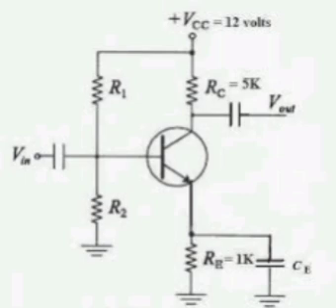It is desired to measure the voltage across the 50 kilo ohms resistor in the circuit shown in the figure. 2 voltmeters are available for this measurement. Voltmeter 1 with sensitivity of 1000 ohms per volt and voltmeter 2 with sensitivity of 20,000 ohms per volt. Both meters are used on their 50 volt range. Calculate the reading of each meter.